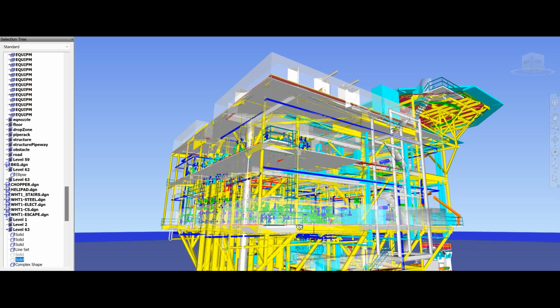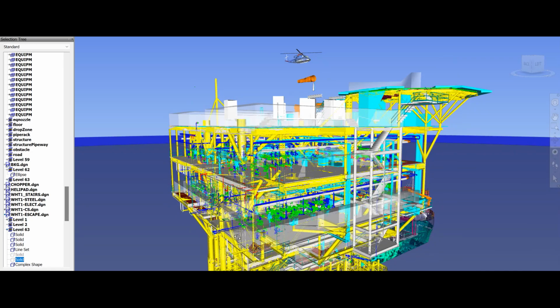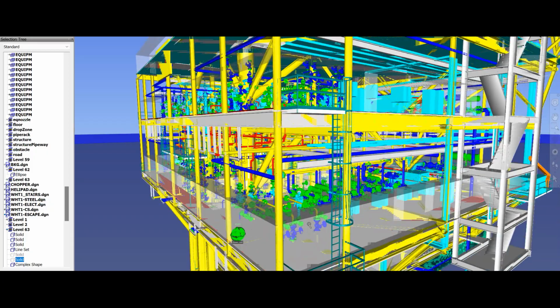Then we have the splash zone where we have the monel sheathing, and monel sheathing is a cladding type of thing to protect against the splash. Then there is a riser, and the riser is connected with a flange at the bottom, and that flange is connected with the swivel flange with the pipe. If it is a flexible pipe, then there will be a swivel flange, otherwise a normal flange, and the pipeline is connected with the bottom of the sea. Again there is a network of the pipeline.